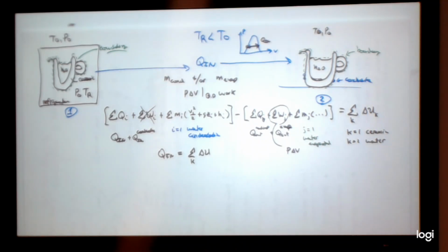Because it's only going to be 20, 30 degrees, and the thermal expansion coefficient is 10 to the minus 6 per Kelvin. So it's really small. It's going to be microns, you know, width of hairs, expansion. That's how much it would expand. So you wouldn't be able to measure it.